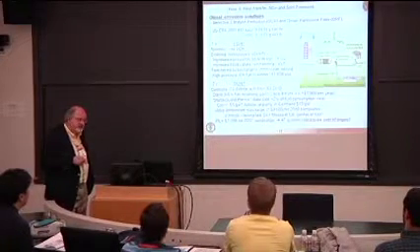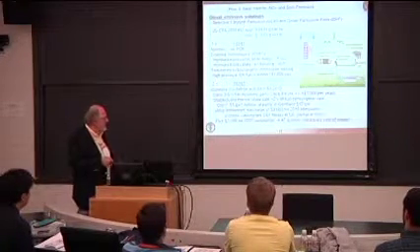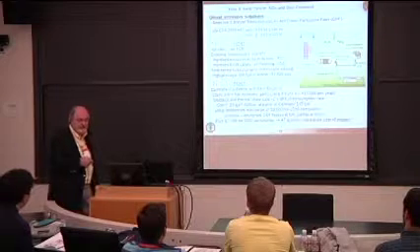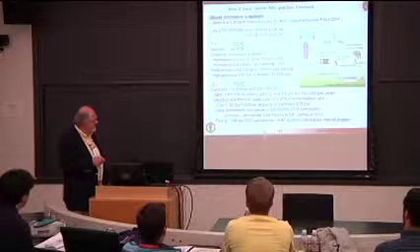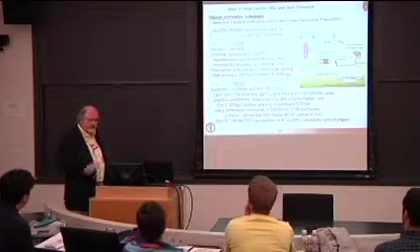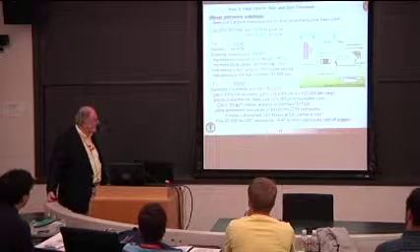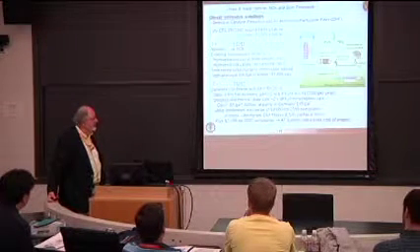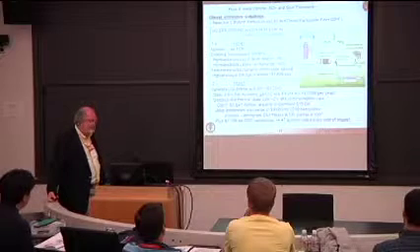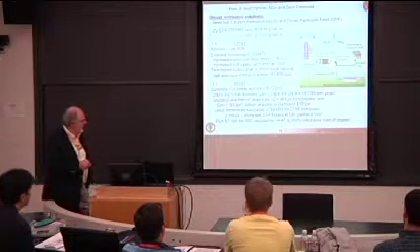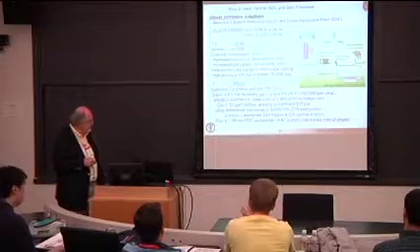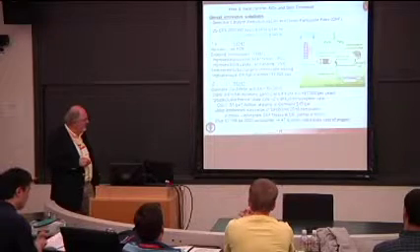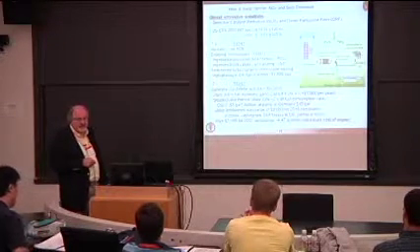It's a mixture with water, so it freezes. It also gasifies in high temperature environments. So keeping this dose at the appropriate constant water to urea ratio is very, very complex and requires all sorts of control.